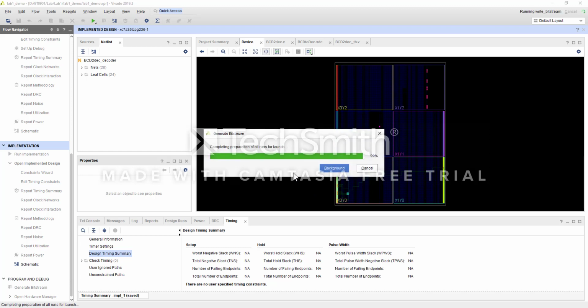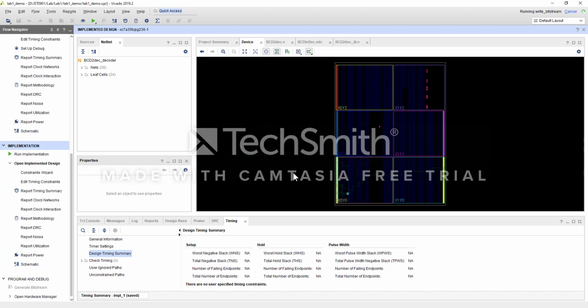This is not as straightforward as microcontroller programming. You probably just need to generate a hex file and then you can program it directly. But for FPGAs, we need a few procedures for the bitstream to be generated. The bitstream is essentially a binary file, similar to the hex file, which can be programmed onto the chip.